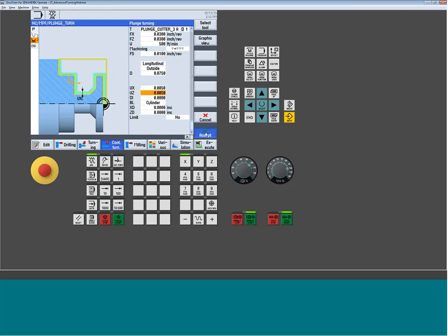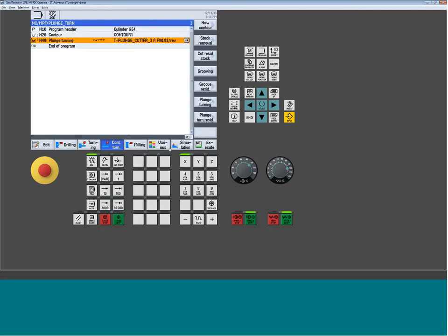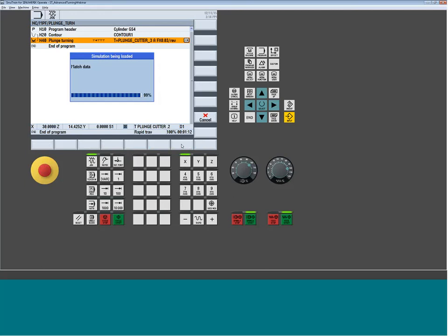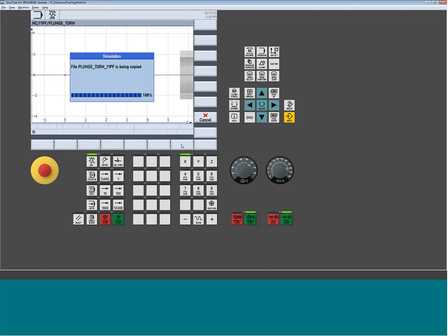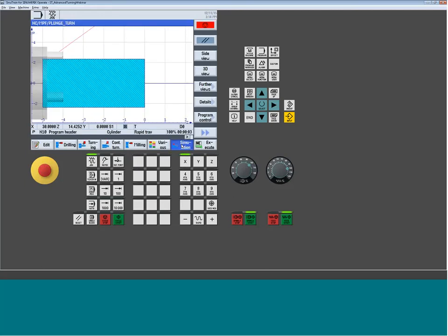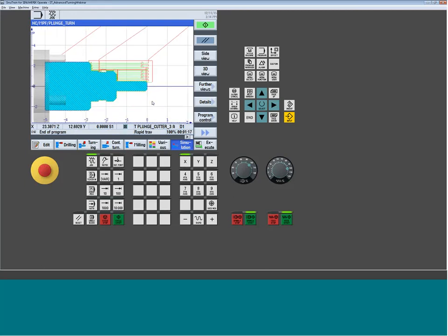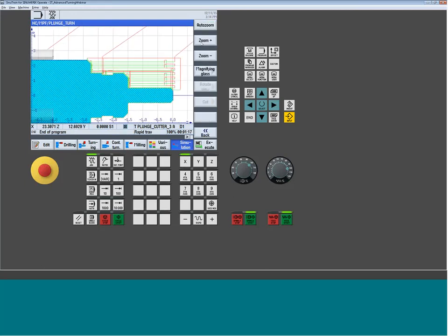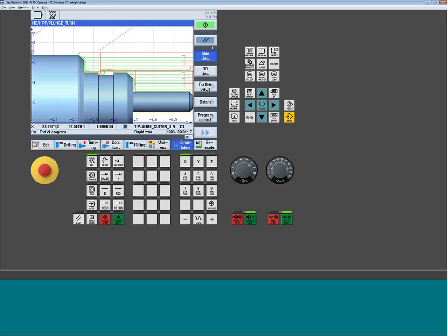But as you fill it out and you accept it, now the end resulting cutter path, however, is significantly different than what you just saw. So now it's going to feed across, down. Now I want you to look at the little bit of the dance it's doing at the ends. It's actually backing off a little bit, and I can slow that down. We'll let it finish, and we'll zoom in. And maybe we'll put it to the full side view. And let's just slow it down here a little bit.